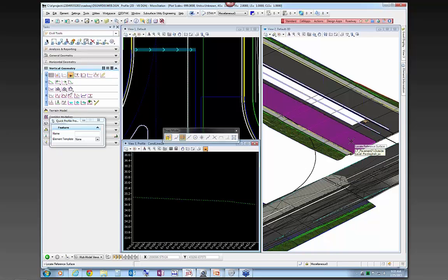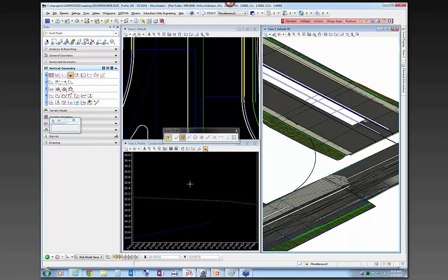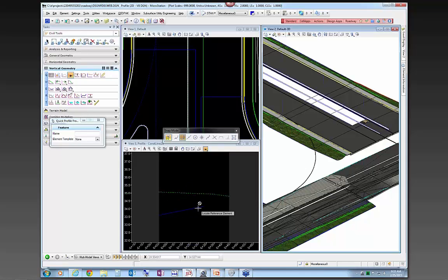If you wanted to be able to select an entire surface, you would have to set your corridor stage to the top mesh, and then you could just pick the entire top mesh and it would basically show the profile for the whole thing. I'm lazy, I don't want to go back and reset that corridor design stage, so I'm just going to click this surface, and then if I reset, you'll see that it draws that part of the proposed surface on this profile.